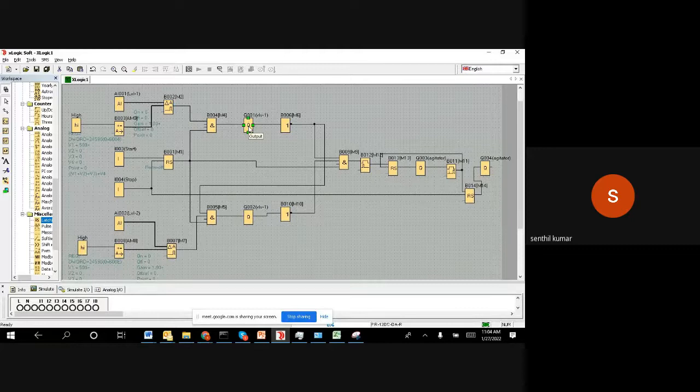First one, yeah, we achieved that, right? So now, as and when the level decreases, once it goes less than 500, this becomes off. Once it becomes off, here we have a 1, here we have a 0. Since an AND gate requires both inputs to be 1 to turn on, this will go off. So our logic is achieved. Since the level is less than 500, we closed it.